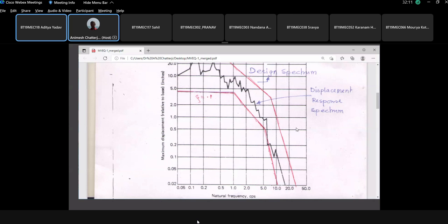We have friction liners. There are two reasons why the gap is there. One is that the horizontal part of the flyover expands due to temperature change. If we cement it, its expansion will be restricted. So we keep a liner so that the horizontal part can slide forward or slide backward. The column will not object to it.